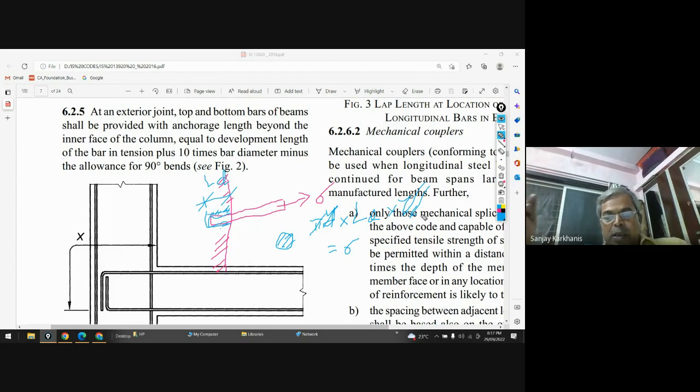That is the frictional resistance offered by concrete. But once you have defined your grade of concrete, let's say I'm using M25, then this is also fixed. D is also not changing. Sigma depends on external forces. The only thing available to me is Ld, and that's why I'm trying to define Ld like this, so that the bar will not get pulled.